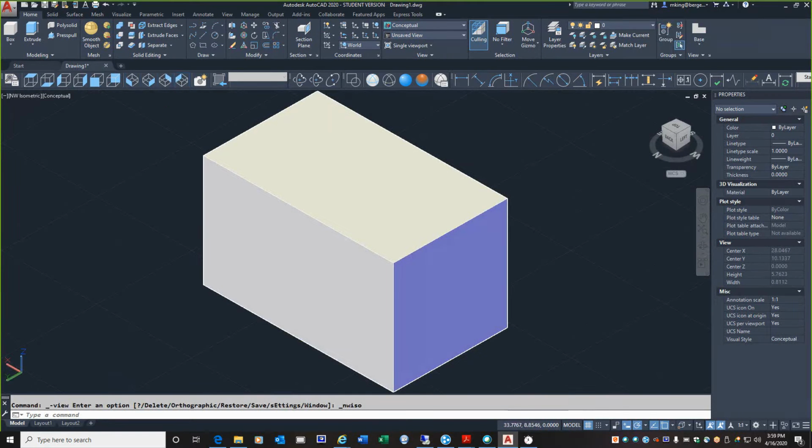Which direction am I looking at if you just walked in the room? Well, enter the UCS icon. This is very important now. This is going to be like a lost person in the woods with a compass. They need to go north. How do they know where north is without the compass? So if you look at that, Z, or your thickness, is always going to be pointing up out of the ground, and it's really the X and the Y that you want to understand.